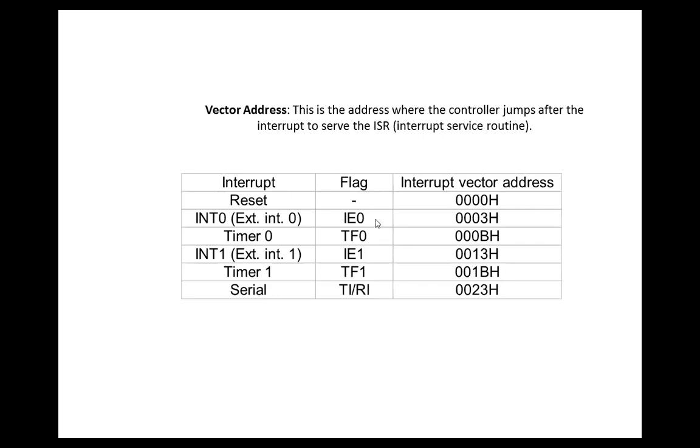So TF0 and TF1 are the overflow flags. Overflow flag means what? We're discussing the overflow flag in the 8051 flag register. Suppose you design a square wave of 2 megahertz or 3 megahertz, for which you have to calculate the timer time. You have to convert this frequency in hertz to the timing.